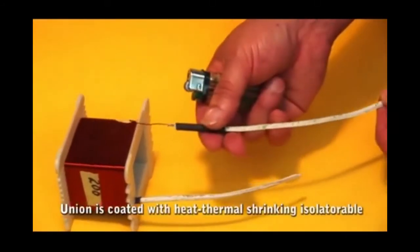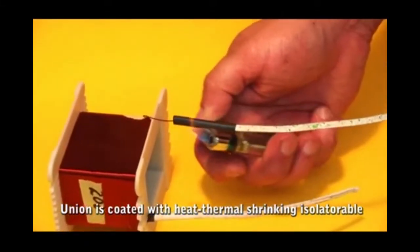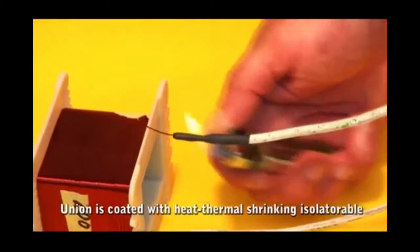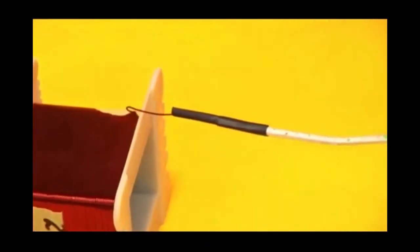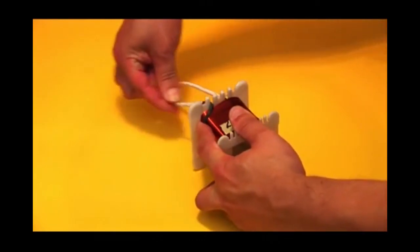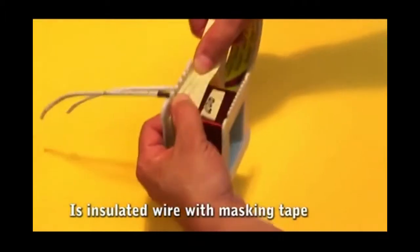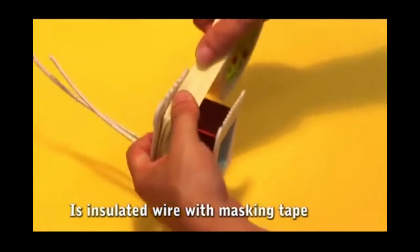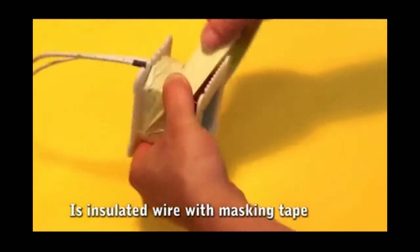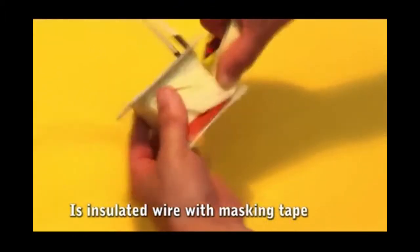We cover the union with 3 mm thermal shrinking insulator spaghetti and apply heat. Insert the cord into an outlet slot. Insulating the primary winding: the primary and the secondary windings are insulated from each other with masking tape and wax paper or pressboard.